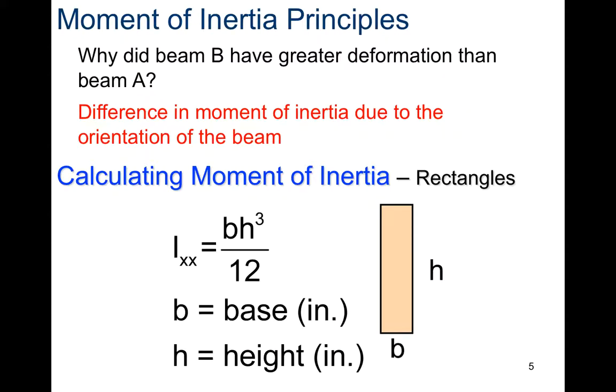Okay, now here is the calculation, which I know looks a little bit of a mess, but it's really not too bad. So I, with the two little x's next to it, stands for moment of inertia. And that's calculated by base times height cubed, divided by 12. The only thing that's being cubed there is the h, just height. Base is not cubed. You're measuring the base in inches and the height in inches, and that's where that dividing by 12 is going to come into play.